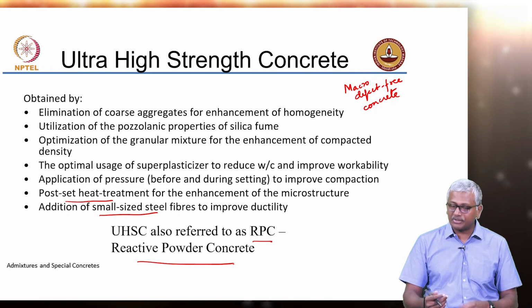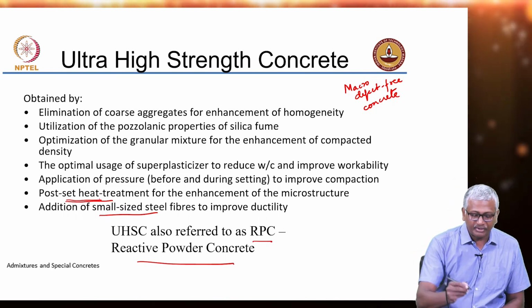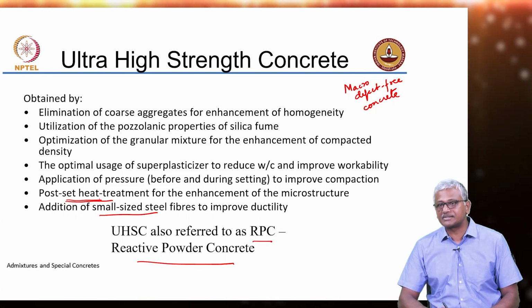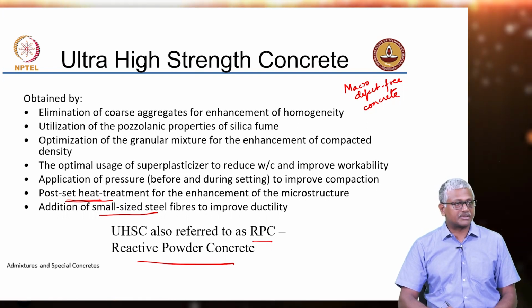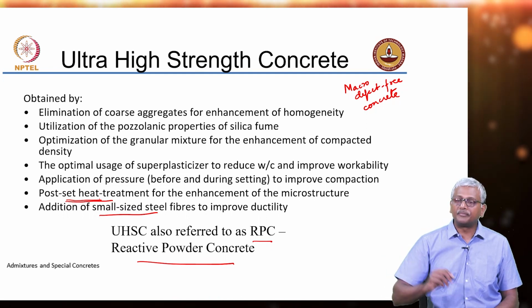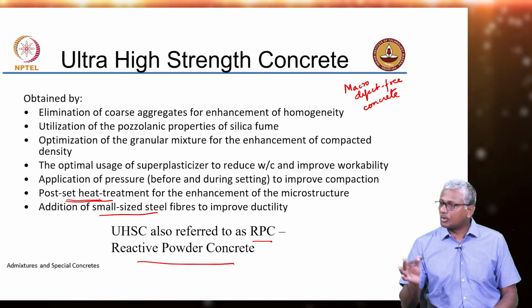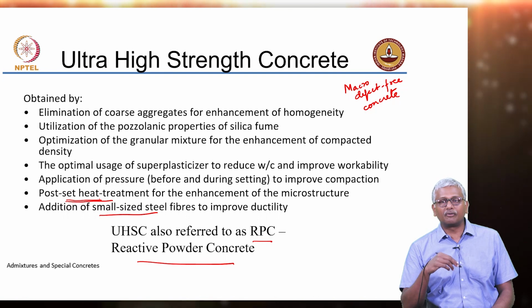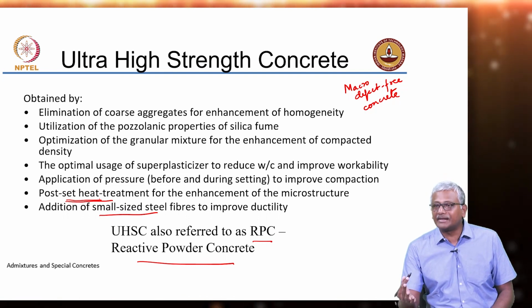And to enhance that hydration further, you can do this post-setting heat treatment that further enhances the hydration characteristics without really compromising on the overall long-term strength. It's a little bit contradictory to what we've been taught before. No? We've always been told that the more you hydrate, the better the strength.